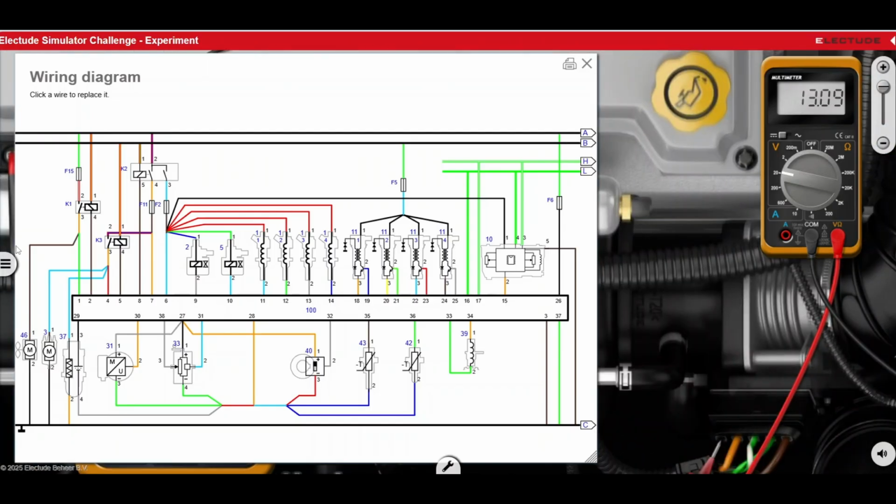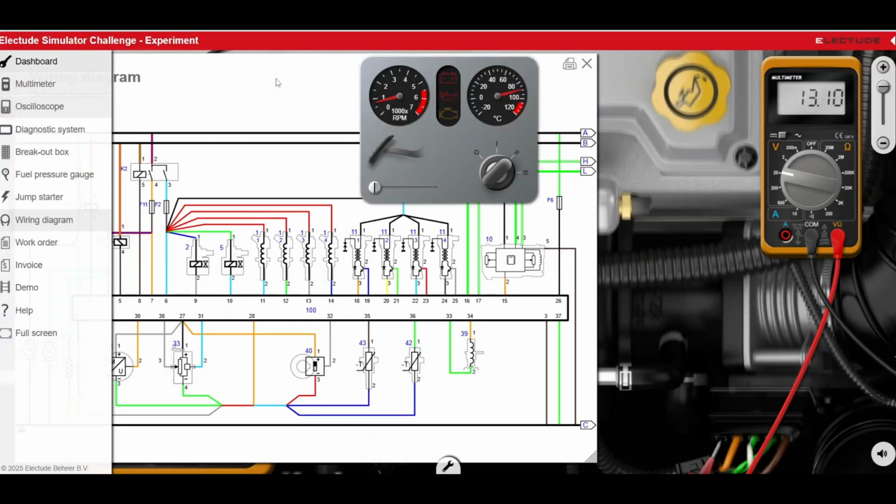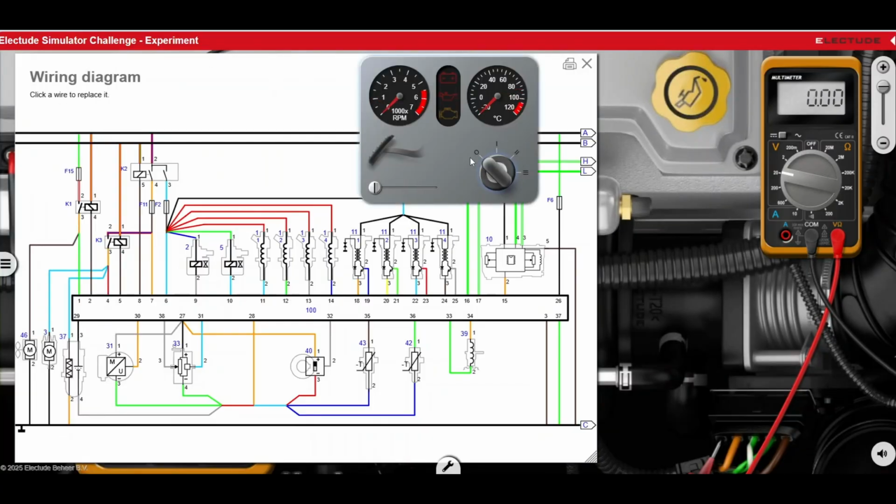If you were to stop the engine running but leave the switch on, I cranked. Let me stop there. Because the engine is not running now, you have 12 volts. When the engine runs, you get charging voltage over there.